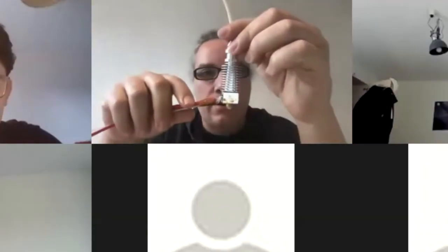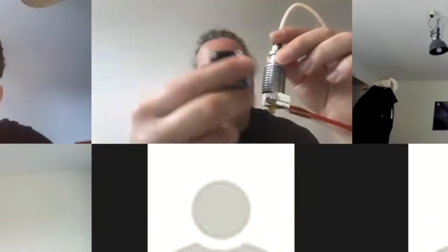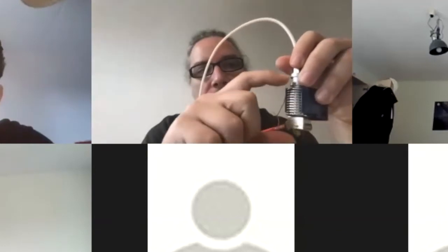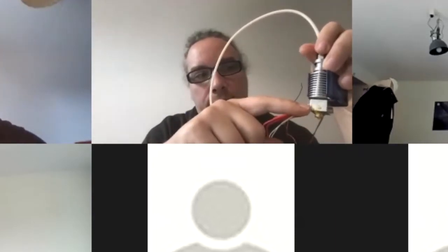So this is the hot end of the printer. This part here is the heating block. You can see two different cables coming from here. This one, the big one, is for increasing the temperature, and the small one is the temperature control. The top part usually has a fan on it, like this one, because in this part you want your filament to be still filament-like. If I have molten filament around here, it's really difficult to push it through. So I want to melt the filament only in this small part here. This part is still the cold part, and this one is the hot end part.